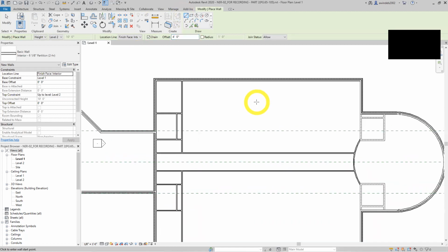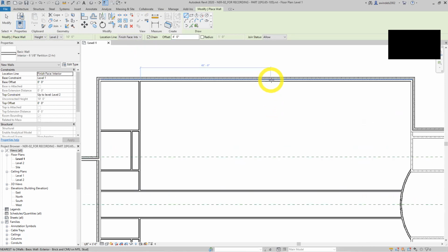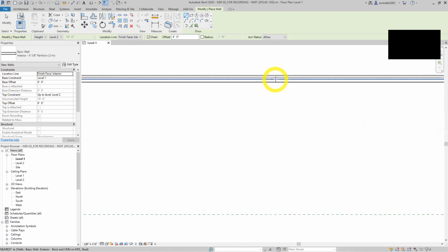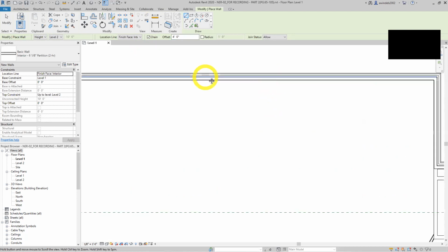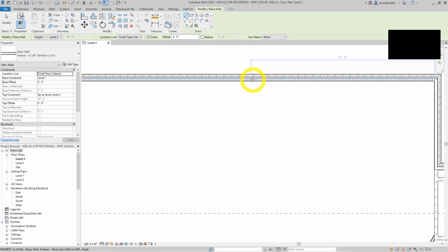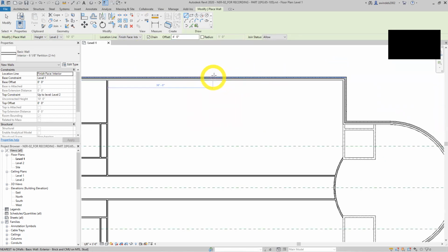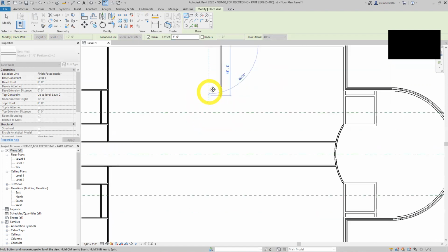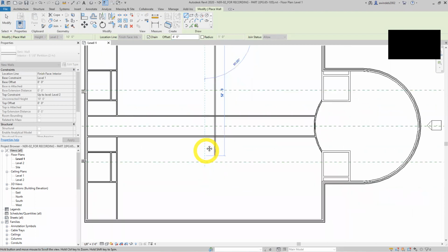It doesn't matter if we start to the top or bottom, but this one wants to start at the top. So we're going to hover in here until it hits a midpoint. I want this in the midpoint of this wall. There we go. There's the midpoint snap. That's what we want. And we got the offset of 4 on, that's key. So when we're looking for our origin point to offset about. There, it did it. So my dotted line, that's what it's offsetting about.